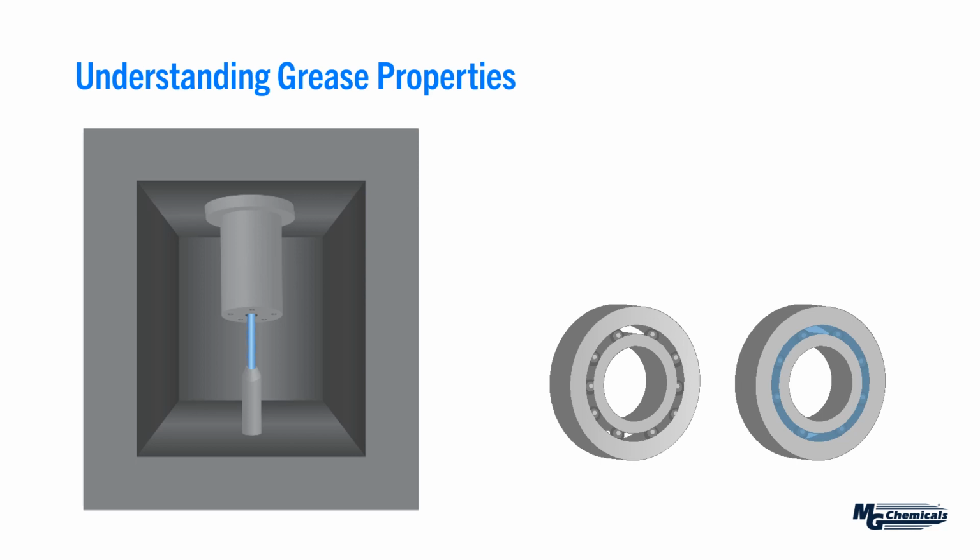From there you continue to hit that bearing with the jet of water for 1 hour. What you're measuring is the amount of grease that has washed out from the water pressure you've subjected it to. So it's simply a before and after test. You take the weight of the grease before, you reweigh it after it's dried afterward, and you report the amount as a percentage of the original weight that has been washed out from the test condition.